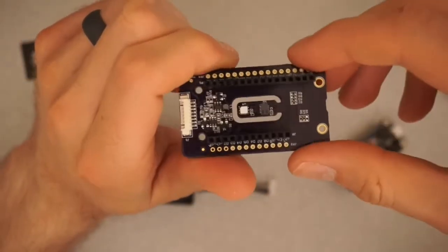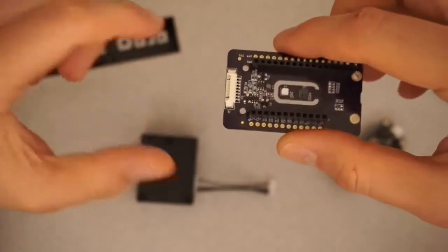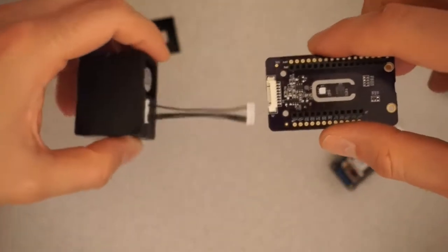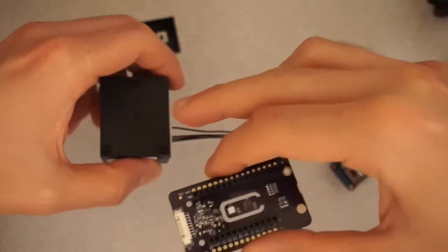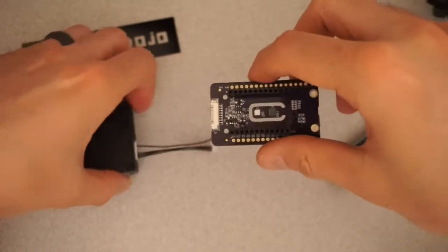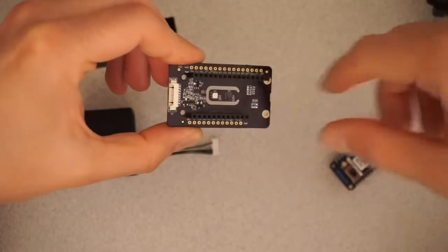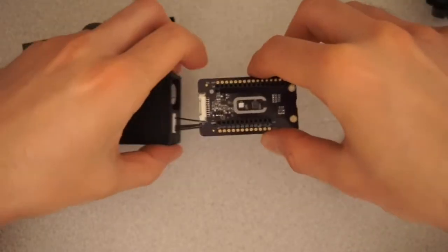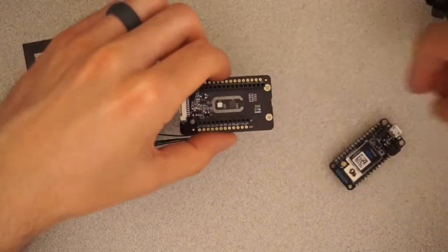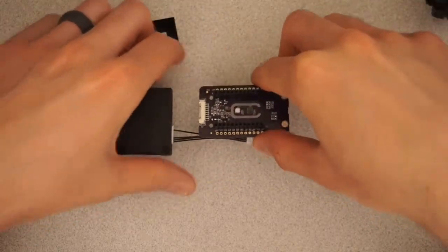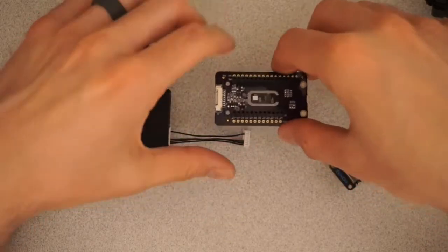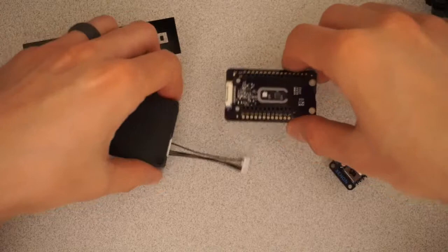Obviously, you can see the board design. The way it was intended is this: you can put the particle sensor here, plug it in. The air flows from here out that fan, and then across these sensors. So if you had it in an enclosure or something, you have a nice airflow across these sensors and then out the exhaust port or whatever. That way you have a nice constant airflow or fresh airflow whenever this is turned on.